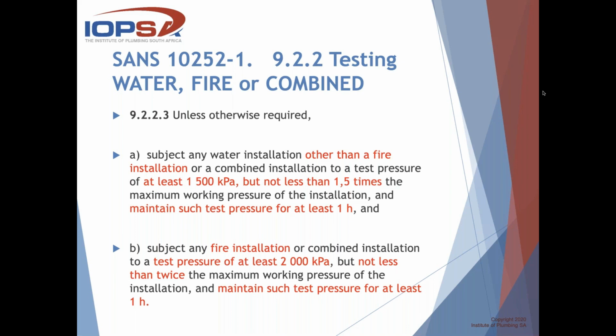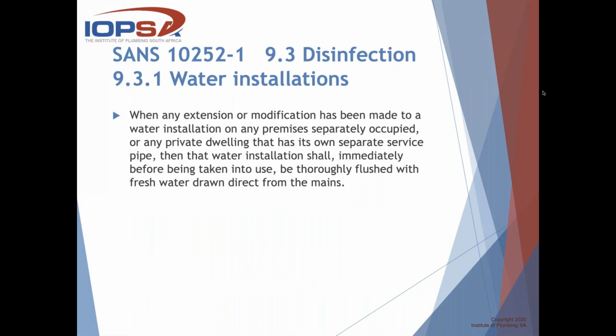So the next step, we have had cleaning, inspection, test, pressure testing, disinfection. When any extension or modification has been made to a water installation on any premises separately occupied or any private dwelling that has its own separate service pipe, then that water installation shall immediately before being taken into use be thoroughly flushed with fresh water drawn directly from the mains. So disinfection, the next step, and here they talk about storage tanks.